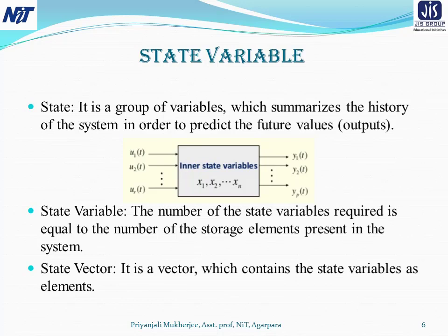So overall, the state space is considered as the minimum number of state variables which are necessary to describe the dynamics of the control system, and the n-dimensional space whose coordinate axes consist of the x1 axis, x2 axis up to xn axis is called the state space. For two-dimensional cases, the state space is reduced to the state plane or the phase plane, and any state can be represented by a point in this state space.